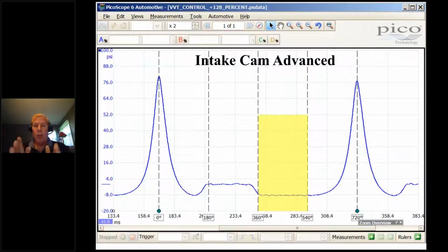Why? There's two primary reasons why pressure will change like this inside of a cylinder. And they are, in no particular order, the amount of pressure that's in the cylinder and or the intake manifold, and when the intake valve closes. And in this case, it's more about when the intake valve closes. I'm going to move back a little bit from my camera, so hopefully you can get a better sense of my hand here. But imagine for a moment, my fist is a piston and I'm stroking a cylinder. I'm going from bottom to top.